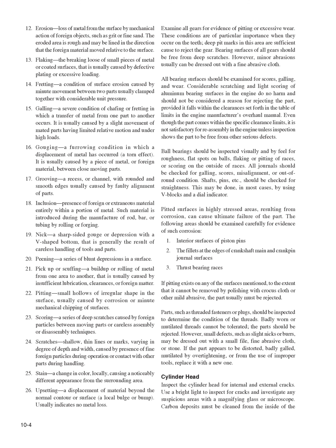13. Flaking, the breaking loose of small pieces of metal or coated surfaces, is usually caused by defective plating or excessive loading. 14. Fretting, a condition of surface erosion caused by minute movement between two parts usually clamped together with considerable unit pressure. 15. Galling, a severe condition of chafing or fretting in which a transfer of metal from one part to another occurs.